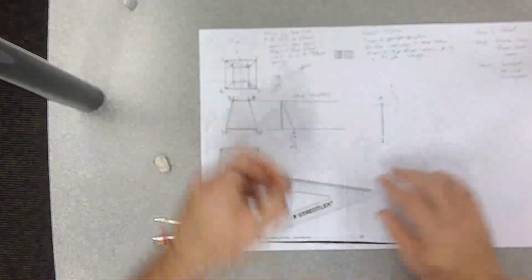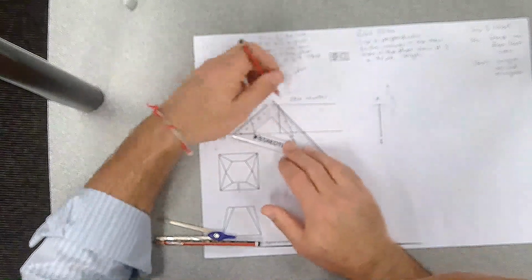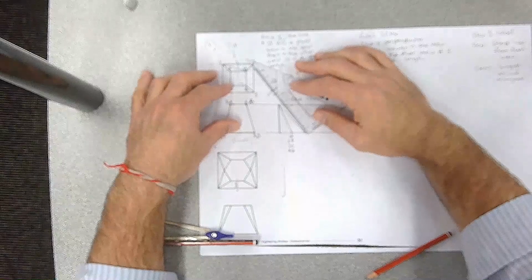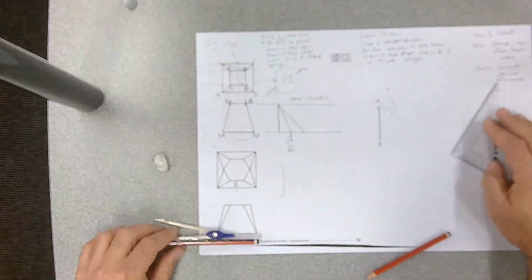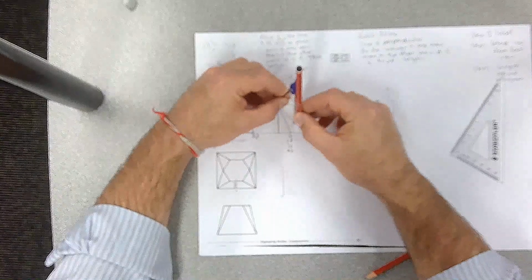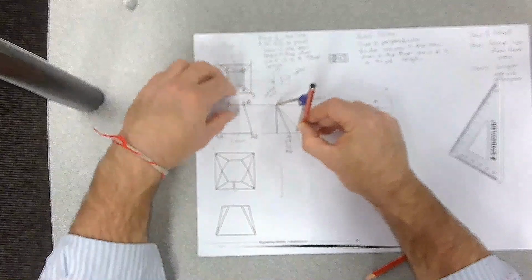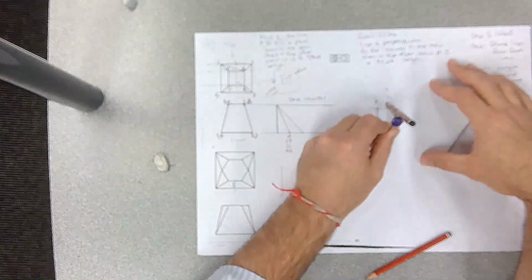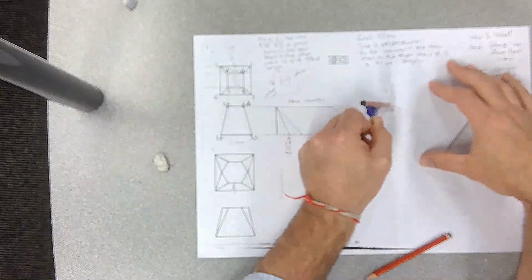And once we've swung our arc, we draw our true length. Okay, now we're going to measure it, and we find out that it is 5 centimeters. So we set our compass on here, and we're not going to need to really measure it, because once we do our 2 swings, we'll get a point that we can go to. It's 5 centimeters. We're going to put our compass on. We're going to swing our arc.